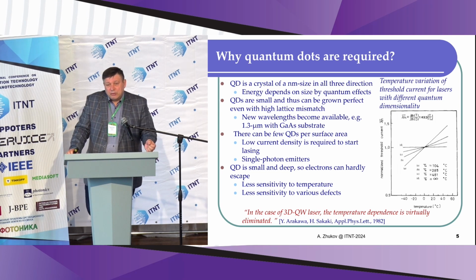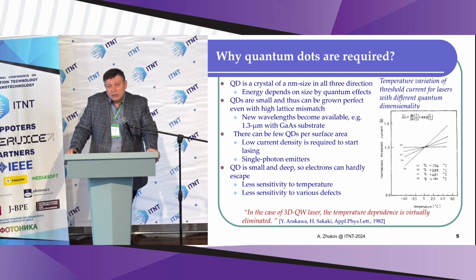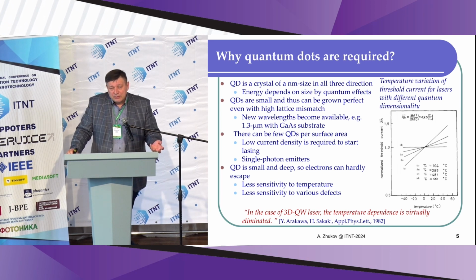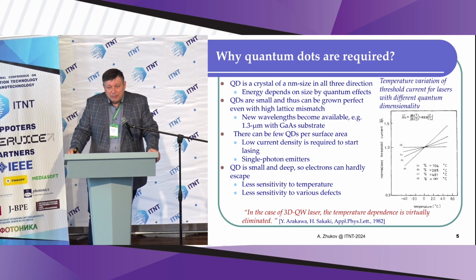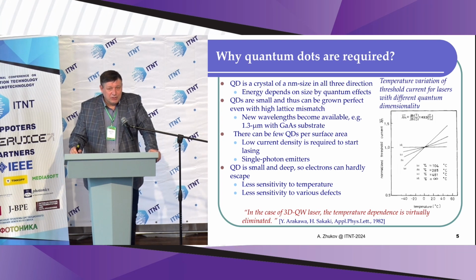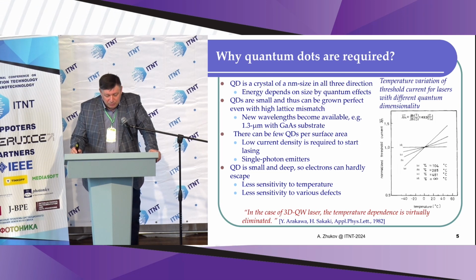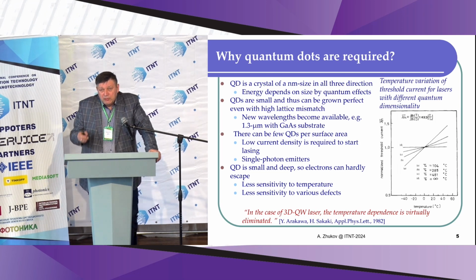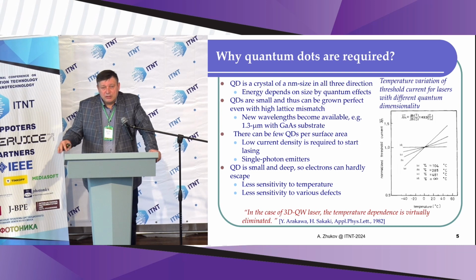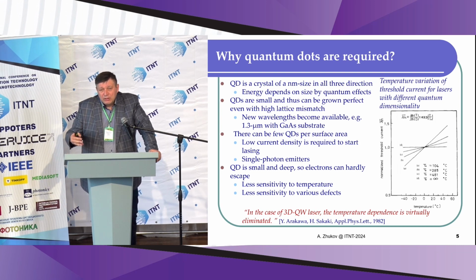Also, because quantum dots are small compared to a two-dimensional quantum well, they can use other materials with higher lattice mismatch, for example, compared to a quantum well. This gives additional flexibility in choosing the materials and their optimization for different purposes. And also, especially for laser applications, it is important that quantum dots usually have quite low surface density. So it's easier, compared to a two-dimensional quantum well, to excite quantum dots and make them